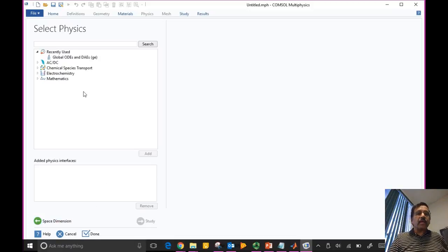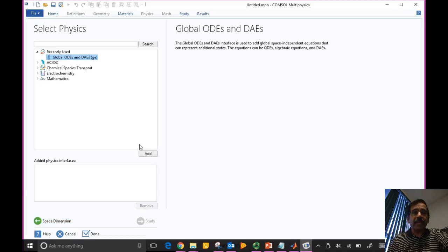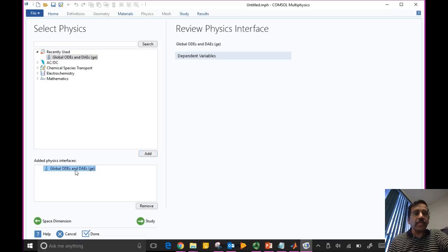So you have selected the space dimension here. If you want to go back and change it, you can do that. So let's select global ODE and add that. Okay, so it adds that. And you can then go to study. So the wizard is guiding you towards how to assemble your problem.